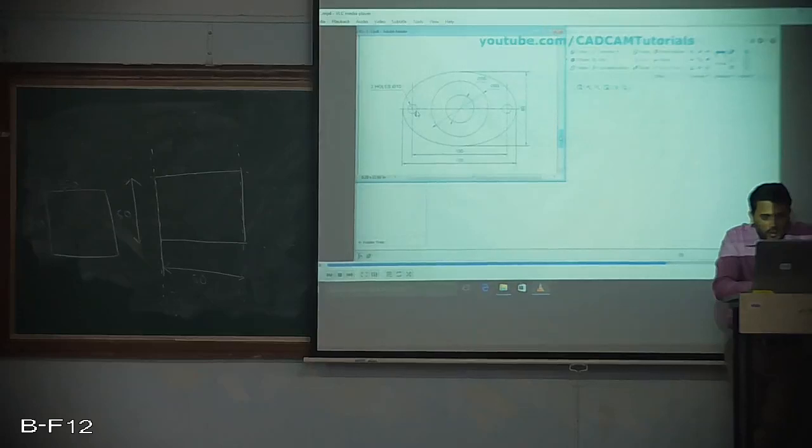and then you can dimension between this axis line and this edge as 10, and here from this axis and this edge as 10, and then we can draw a horizontal center line exactly at the middle point of the axis, and then you will get two intersections. There you can draw the holes or these circles by using the circle command, and then you can use one more